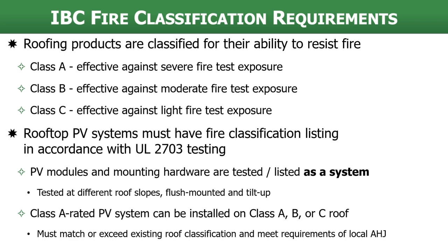And over the past 10 years or so, rooftop PV systems have become so prevalent. I think in about 2012, it began when they were required to have a fire classification listing in accordance with UL 2703 testing. 2703 testing is the standard for flat plate PV modules and the racking components, including integrated grounding, mounting devices, that kind of thing.